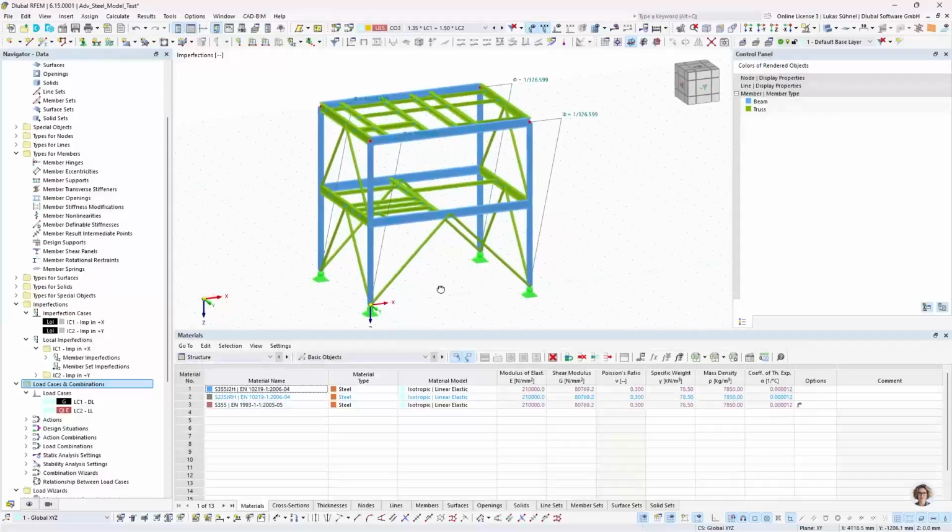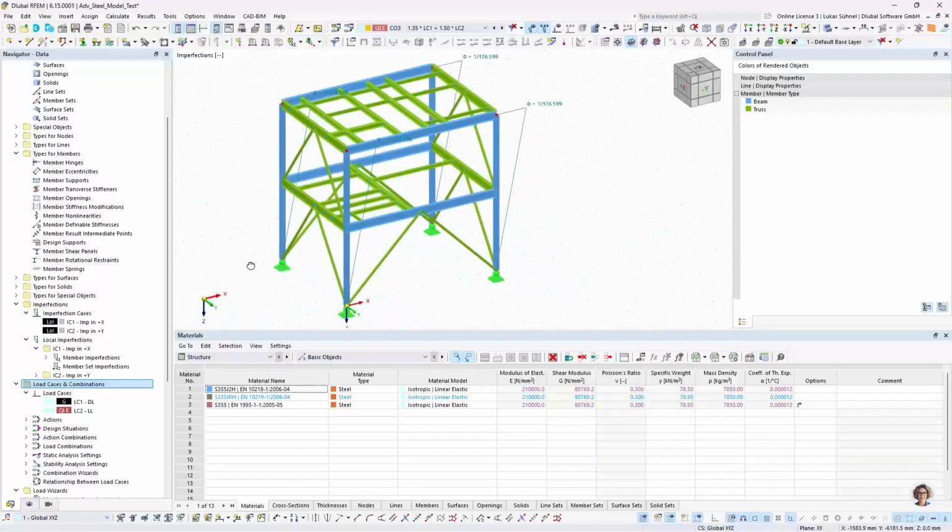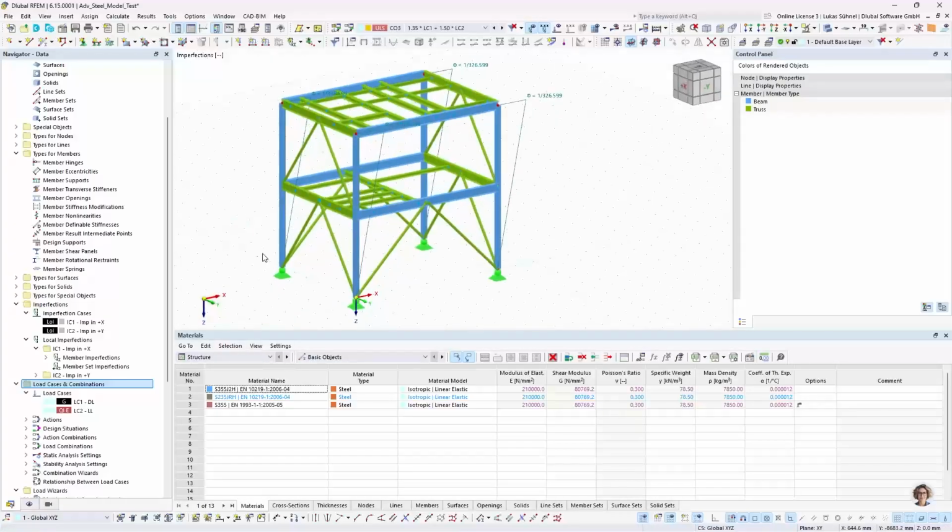All right. And now the last thing that I have to do is I have to assign my stability related information or properties to my beams. And let's start with the columns. There are, again, different design checks that we can use. In my case, I want to use the equivalent member method kind of.